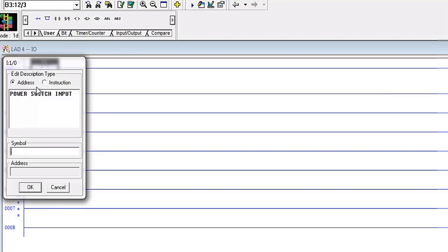We'll be able to see addresses, or depending on the protocol we're using, we'll be able to see symbols if there are symbols. So if this is anything we're going to be possibly referring to in an HMI later on, or looking at from a different SCADA system or something along those lines, we want to go ahead and give it a symbol.